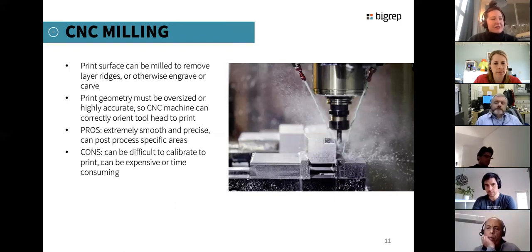It's kind of the same as the sanding. Anything that's a mechanical process of basically abrading the surface. The PLA ultralight is going to be the easiest. You'd almost have to be careful that you don't overdo it because it's more brittle and it has this real foamy structure. Even though it's a rigid foam, it's a foam structure.